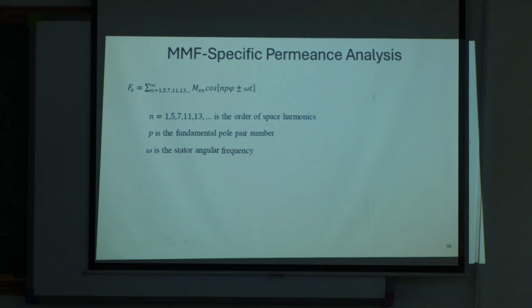So basically, due to the spatial distribution of the three-phase windings, the waveform will not be exactly sinusoidal. So instead of having a wave like this, we may have a wave like this. Okay? Step or staircase wave. And this staircase comes because we have to place only a fixed number of conductors in different slots.